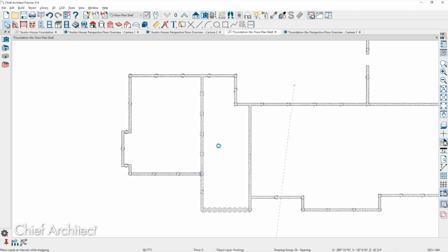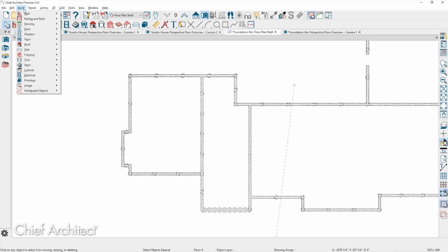Gotcha. Okay, and somebody had a comment they wanted to bring up. Yeah, I was just going to suggest underneath the slab tools under the build menu, there's an option for round piers and square piers. She might try just manually placing those if it's only in a few select areas she needs them. Okay. Thank you. So here's what Phil is pointing out.